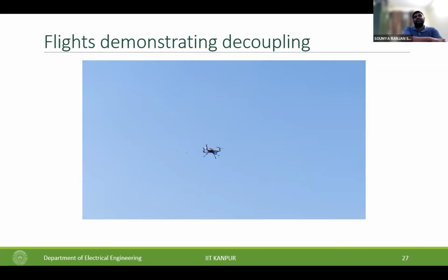So here, when the coupling was there, what we saw was we can fly at a 0 attitude and go to any position. But with these 4 tilts now available, not being coupled, we can now fly at attitudes that may be counterintuitive for conventional quads and still do the same waypoint missions.